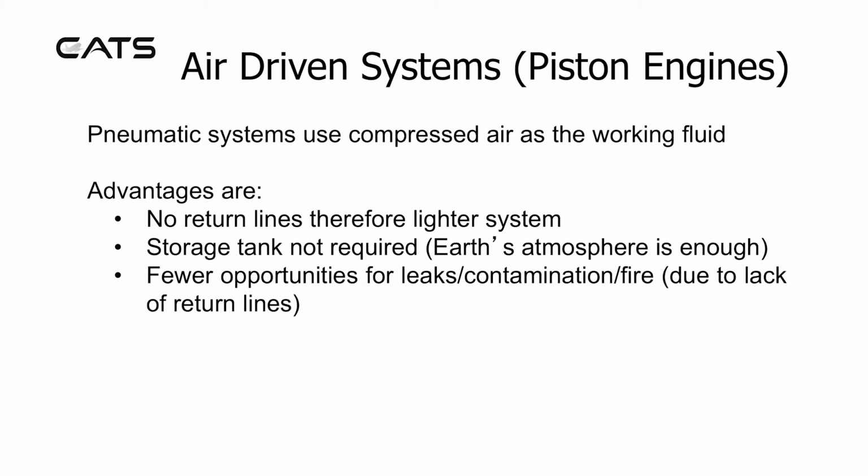Air-driven systems, piston engines. Pneumatic systems use compressed air as the working fluid. The advantages are there are no return lines, therefore the system is lighter. A storage tank is not required, the Earth's atmosphere is plentiful. Fewer opportunities for leaks, contamination, fire due to lack of return lines.